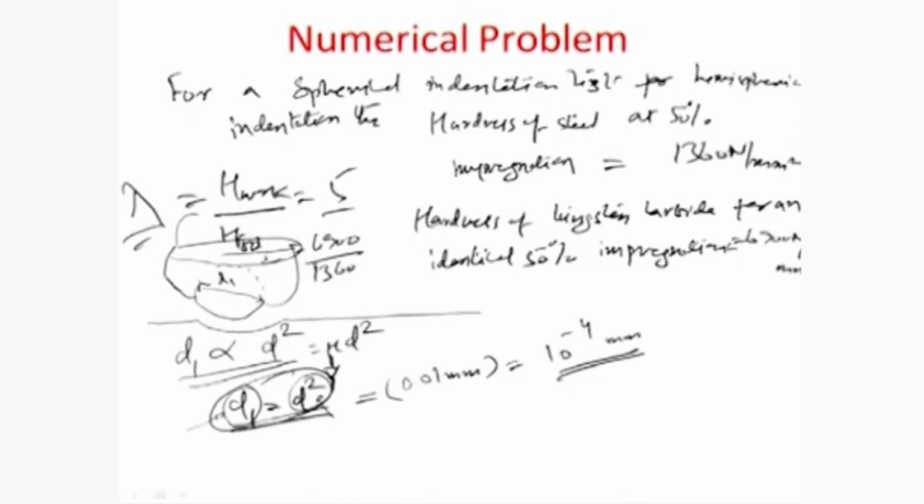So, the grain diameter can be from experiments that Shaw did over a microscope, predicted as about 10 to the power of -4 millimeters. This is the effective grain diameter of the surface. And while doing this, there is an indentation HW that the grain would like to have on the surface here.